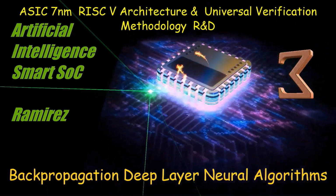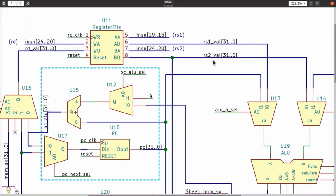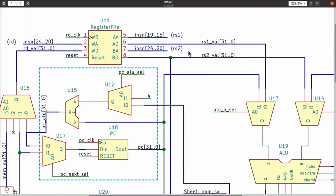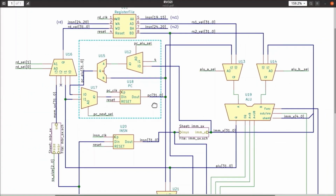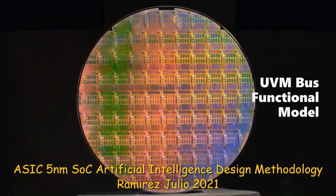Porting the hard macros. For hard IP that was completely synthesized, the porting strategy is quite straightforward. We just resynthesize, targeting the new technology library, and repeat the physical design and timing model generation.